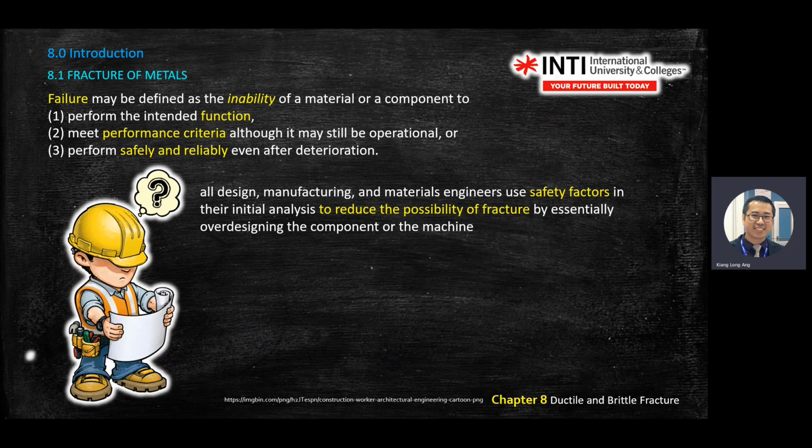After a certain time, you see the black arrow come back to a lower value. That is when it reaches the plastic region, and you see there's necking, a coning. The necking starts happening where the middle section becomes thinner and thinner, and it breaks. So today we'll look at how metal breaks after the plastic region.